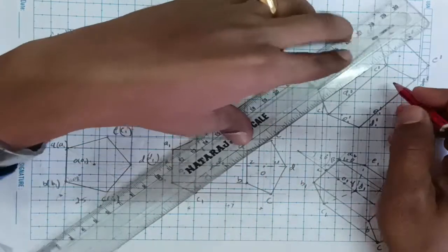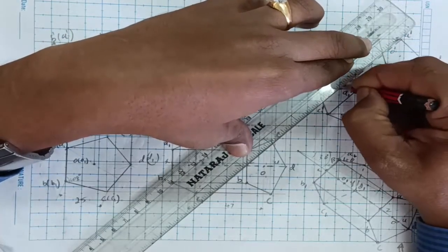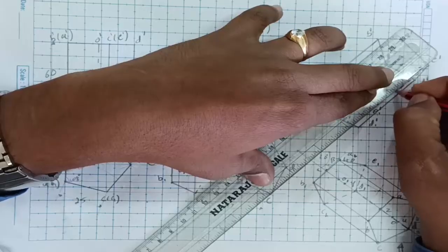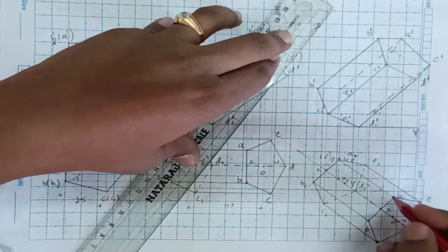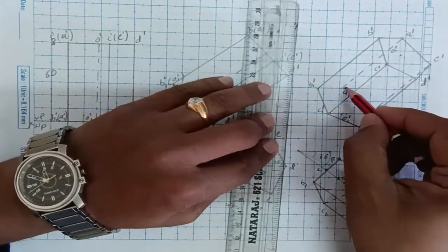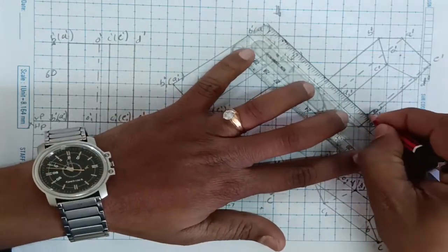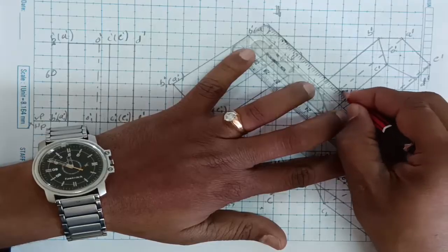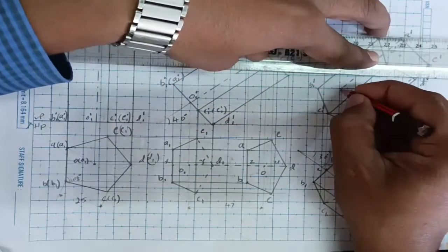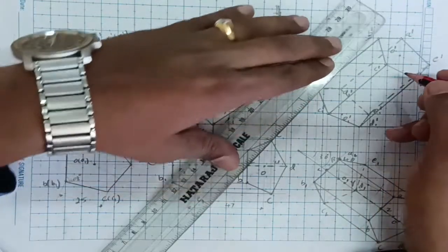Okay, now I am joining A dash. So when I am joining A dash to A1, it is inside the frame, so you make it hidden. And then E to E1, that E to E1 also coming inside, so we need to make that also hidden. And check the endmost. Here the endmost is here, A dash as well as E. That means inside it is coming, definitely that will be hidden. So join those edges also hidden, that is A dash to E dash, you make it hidden, and then E dash to D dash also hidden, and then A dash to B dash is also hidden.